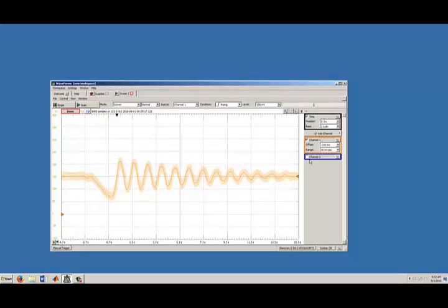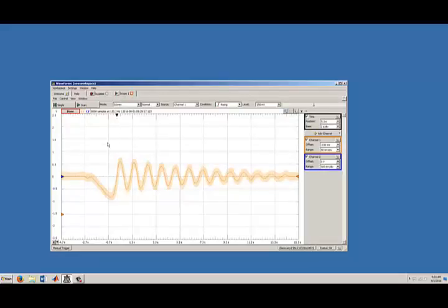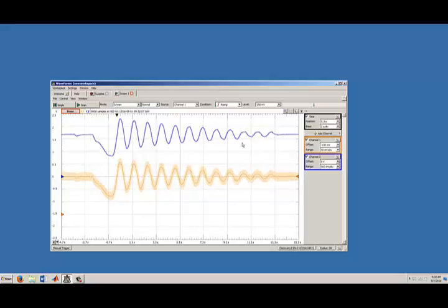I'm going to use channel 2 to measure the response out of the filter. The filter requires positive and negative power supplies, so I need to turn this on, and that will be negative 5 volts. Power is still on. Now let's do another single sequence acquisition. Stretch the spring again and release it. There's my filter data. It's got a much higher amplitude and it's considerably smoother than the unfiltered data.